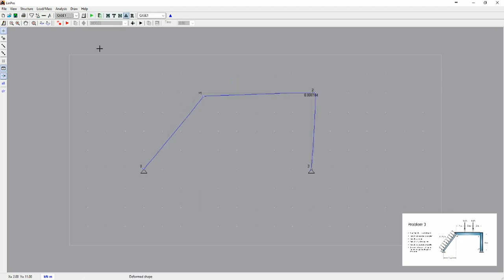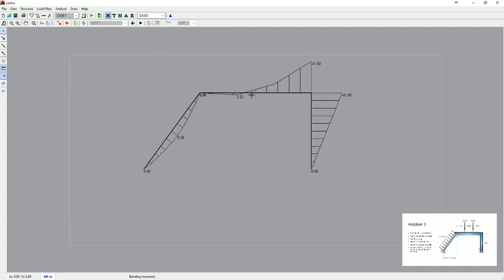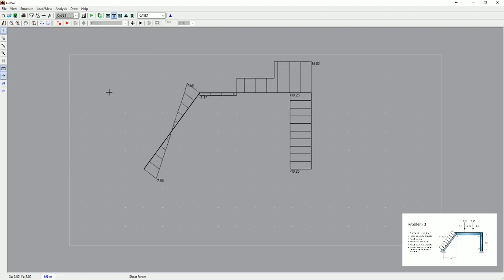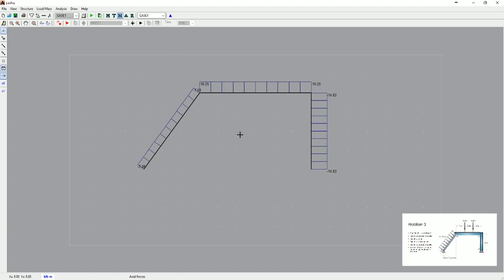Click the green icon. You can see the deflections. You can see that the section has moved to the right. These are the reactions. These are the moments. We can now clearly see the moment pattern on member 1. You can see that it's 3 segmented lines, whereas on member 0 we have a curved line. You can see the shear force diagram. You can see it more clearly. You have the axial force diagram. That concludes the analysis of problem 3.